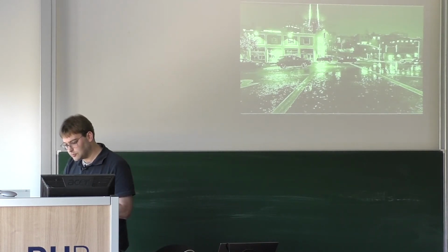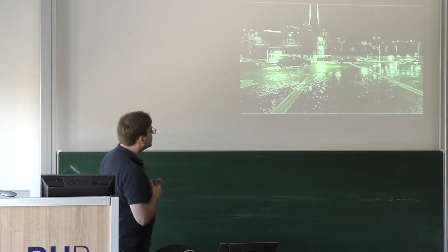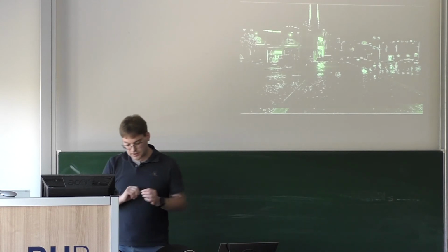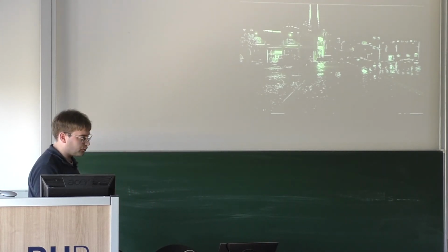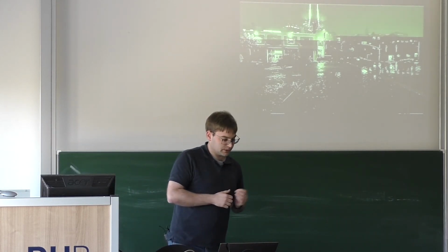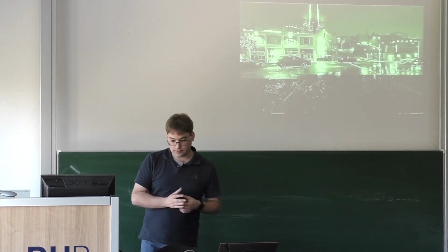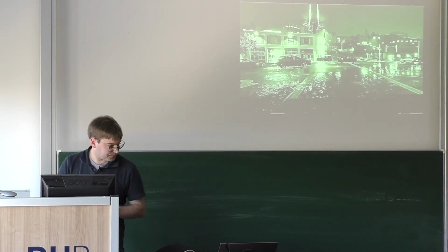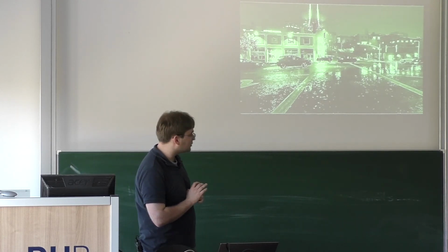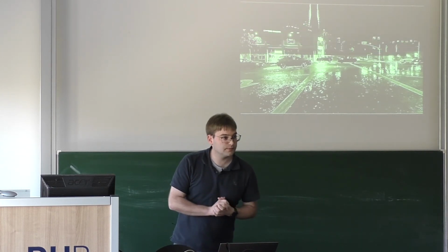So you might wonder why this isn't running in real time, because it takes about 10 seconds for each frame to render. Well, a big FPGA like this is nice, but an FPGA is still a prototyping tool. So each MicroBlaze here only runs at 100 megahertz. But if you think like, okay, we're going to get a real processor here in silicon, this will be running a lot faster. Later on, also in the OVP demo, you will see the same application running, and you will see also there that it's running in real time.